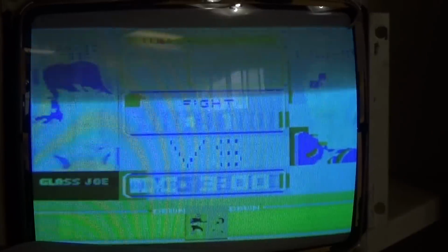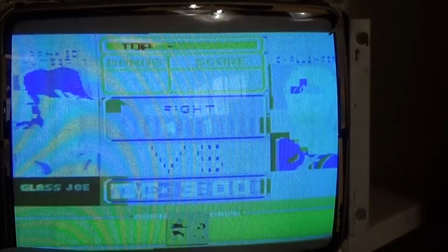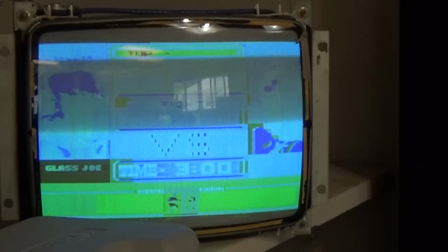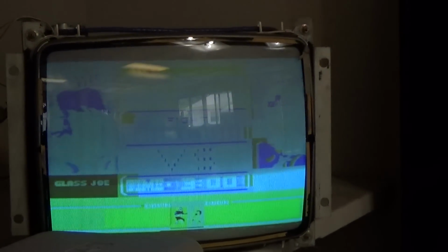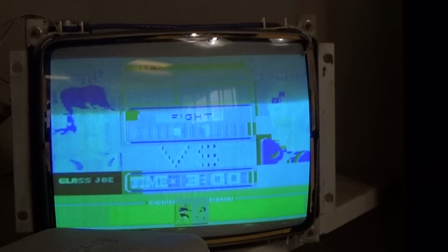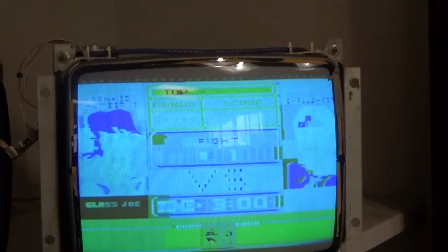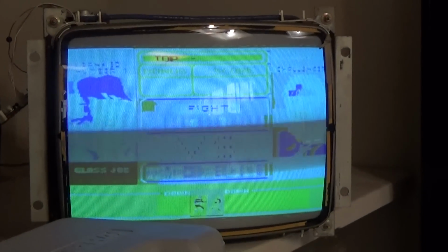When in these areas of the screen, it's got to be just writing out all 11 or FF to get complete white through here or something. I'm going to have to get new PROMs for that. I think that's where we're at. So this one's going to have to go on hold for a little bit. I'm going to order some 82S131s. Burn them. And then come back.